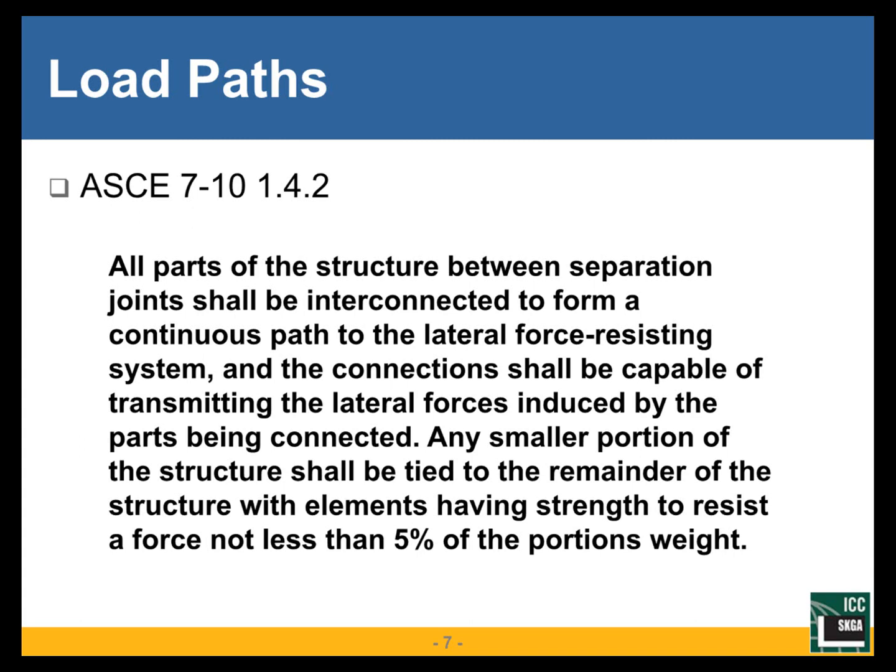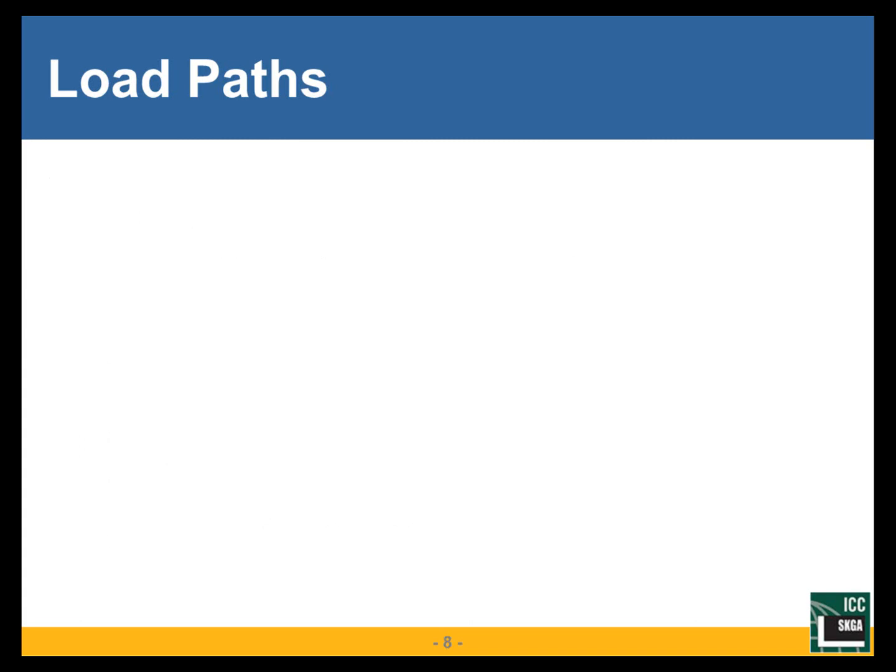In order to clarify that, a clarification was obtained from the ASCE 7 committee decades ago that says, well, it's connected to the lateral force resisting system. The diaphragm is part of the lateral force resisting system. So this does apply. The diaphragm is designed on its own, but here we're getting the loads at least to connect everything back to the diaphragm to provide the lateral support. And it's key, it's part of the integrity and of maintaining load paths for our structure.